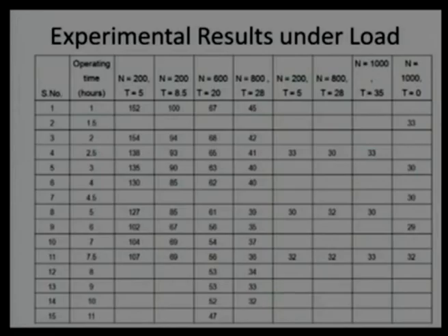Reason being, there will be more clearance and less load, less deformation of surface, that will cause more vibration, less load carrying capacity, and pitting in that case will be much faster compared to with the load. In other words, from Archard's law, as the load increases, wear rate will go up, but when it comes to the lubricated case, particularly boundary lubrication, it is not the case. Quite possibly an increase in the load may decrease the wear rate. It is not in that proportion itself.